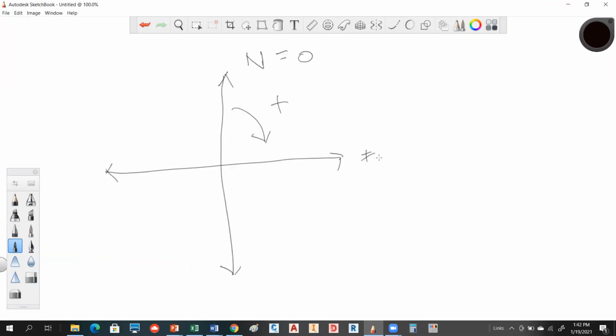So east would technically be 90 degrees. This is going to be 180. That would be due south. Due west would be 270. It's kind of like the zenith system in that respect. Okay. So we don't have quadrants in this system. We can turn azimuths this way, but we would consider those negative. Most people don't do that. You'll never see me do that. So we only use an azimuth going positive this direction.